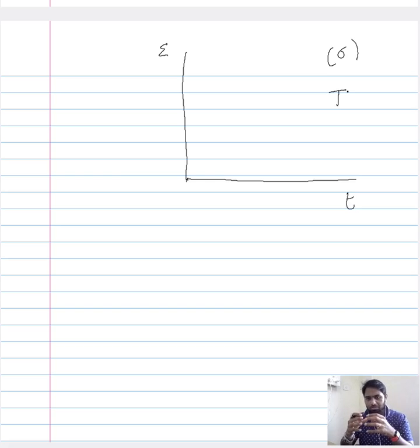So even though the material might exhibit a change in its dimension, the way we impose the condition is such that the stress imposed on the material remains constant all through the testing period. So we relate the stress not to the initial dimension of the material but to the instantaneous cross section of the material. That's how we ensure that the stress imposed on the material is constant.